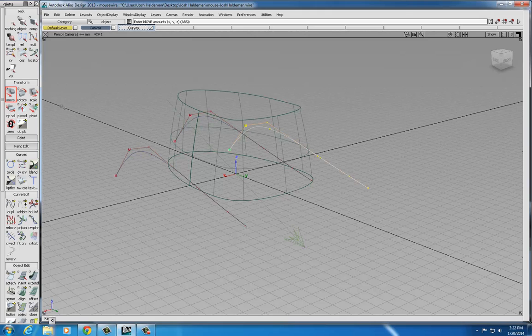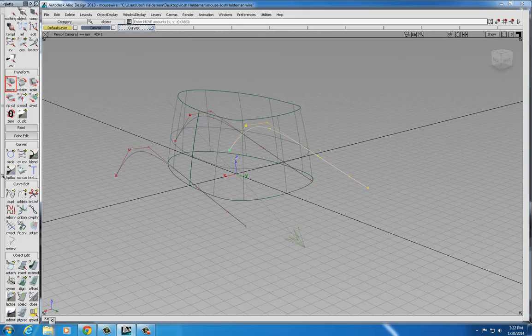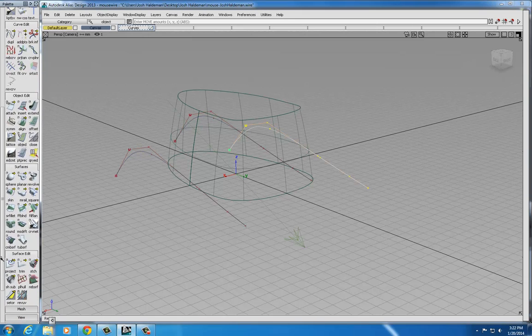Now we're ready to proceed with the next step, which is skinning the three of those curves together to create the top surface. I'm going to do this by scrolling down to the Surfaces menu and choosing the Skin option. Now let me show you a problem with this tool. If I pick a curve, notice the first one selects automatically, then I pick the second one, then I pick the third one, that it actually builds what I want to build there.